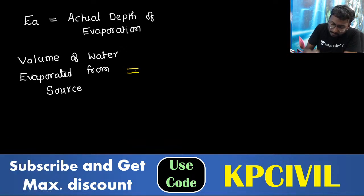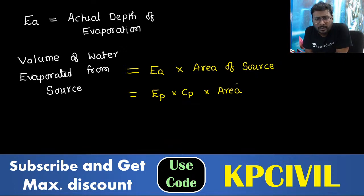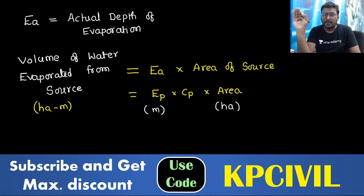Now volume of water evaporated from source is equal to actual evaporation into area of source. So EA we know, EP into CP. So EP into CP into area gives volume of water getting evaporated. You take area in hectares, pan evaporation in meter. Because of that you get volume of water evaporated in units hectare meter. So this is volume of water getting evaporated from source, only one single formula: EP into CP into area.